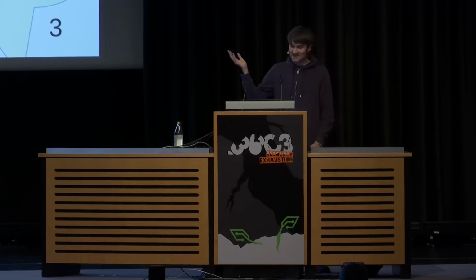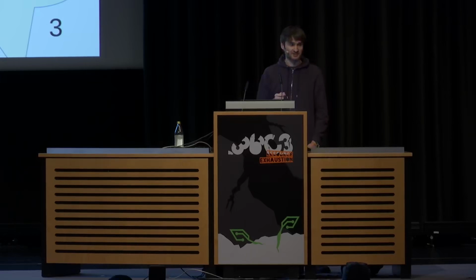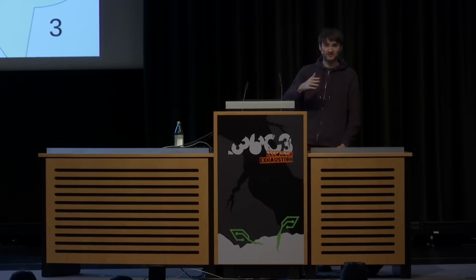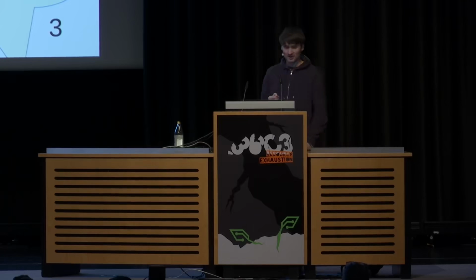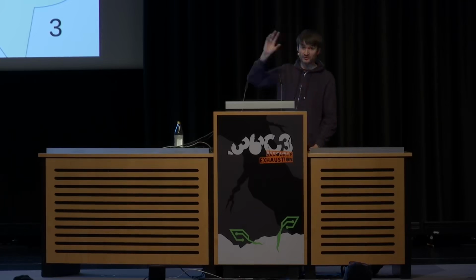But in fact, it's not, because under the hood, on a network layer it seems to be fine, but on a MAC layer of Wi-Fi, there will still be data flowing from the ground to the drone in the form of acknowledgements. So Wi-Fi uses acknowledgements, and so you actually need to acknowledge the package from the drone. And so you have a required upstream from the ground to the drone.